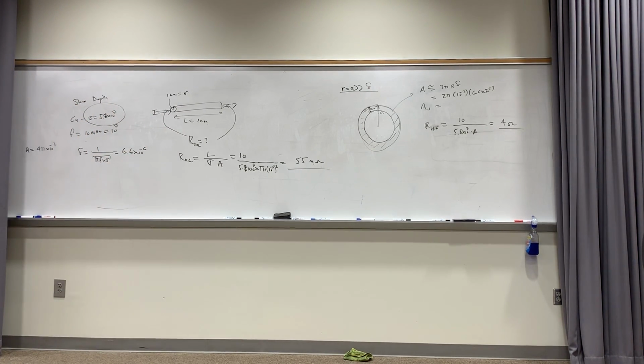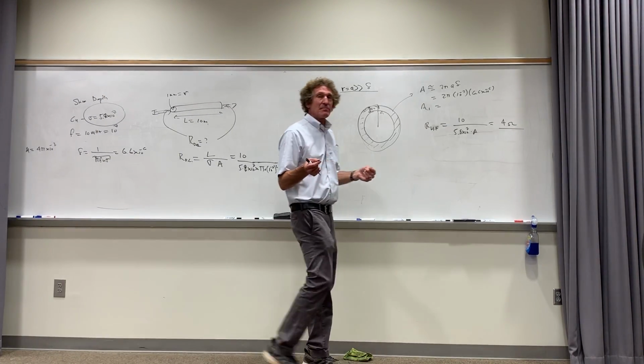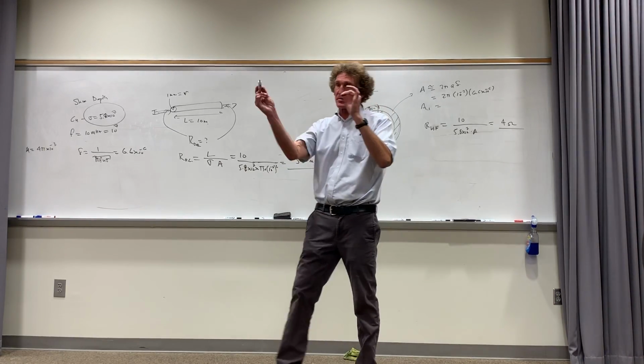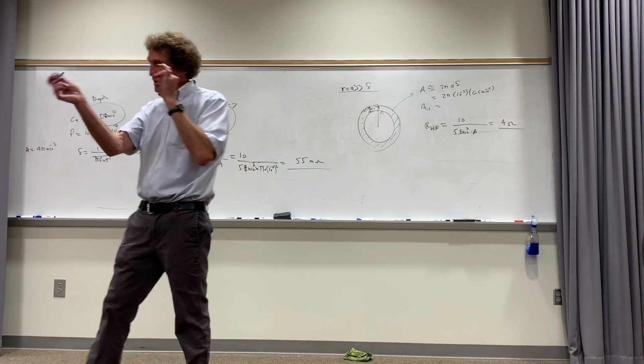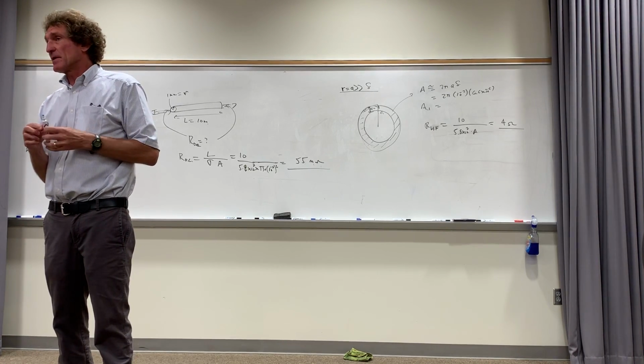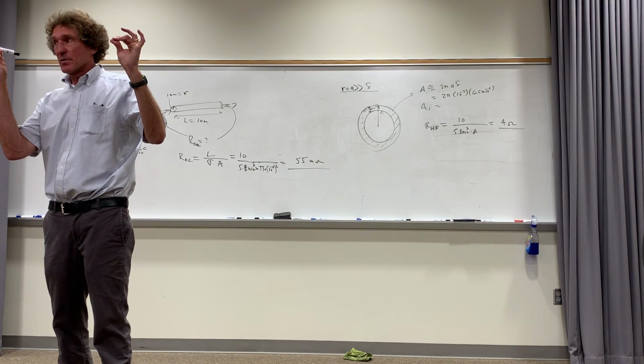So if you're connecting that to something with equivalent to 8 to 10 ohms of input impedance, there's no big drop across that wire. Do you follow me? Even 2 pieces. But when you get up to 10 megahertz, now you have 4 ohms in each wire. It's going to be a differential circuit, right? The current's going to flow down one, come back the other. That's 8 ohms total. If your load is of the order of 8 to 10 ohms, you're losing half of your voltage in the wire. Are you with me on this?